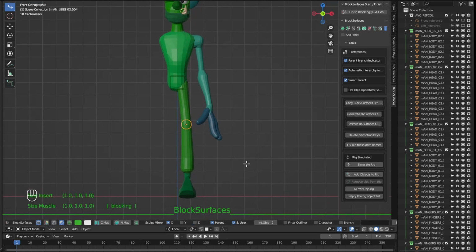Let's see first that we have the option to move through which selected object we have on the branch. We can go through the branch with the up arrow and down arrow keyboard shortcuts. Thus, we move through the objects of the branch. Well, now, let's make the hierarchy between some branches and others. We will make the first object of a branch the parent of the rest of the objects of that branch. It is the one that moves everything. It is the child of another branch, so the whole branch will follow the rest, as when moving the trunk the leg will follow.